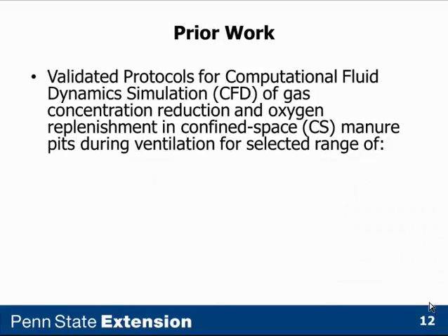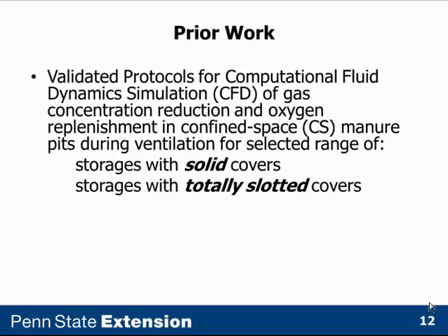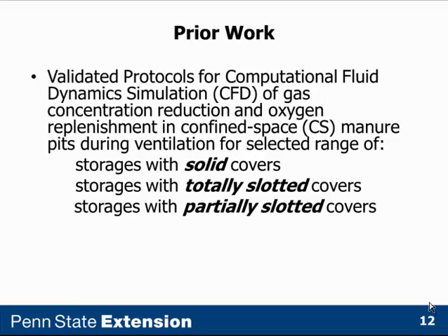In almost a decade-long effort, we developed and validated protocols for computational fluid dynamic simulations of gas concentration reduction and oxygen replenishment in confined space manure pits during ventilation. And we did this for a range of storages: manure pit storages with solid covers, manure pit storages with totally slotted covers, and manure storages with partially slotted covers.